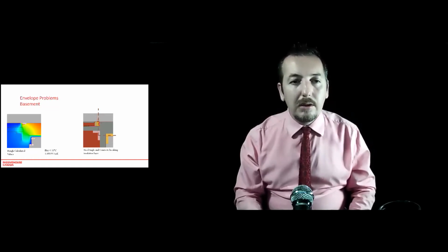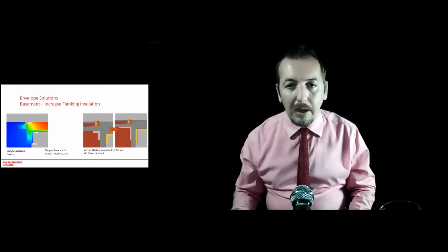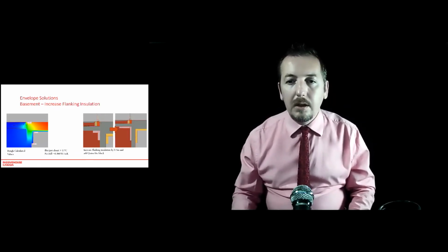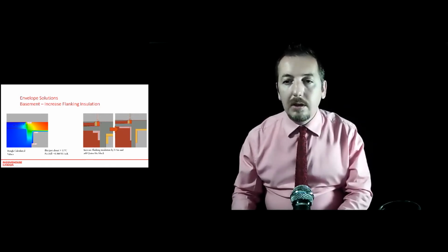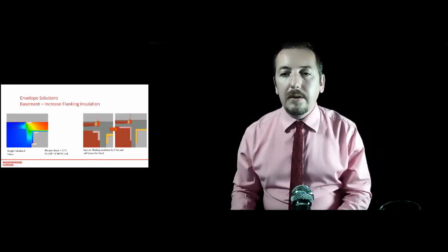Now, we went through iterations to try and retrofit this, and we found that we needed to get to 15 degrees, which is an fRsi of 0.75.